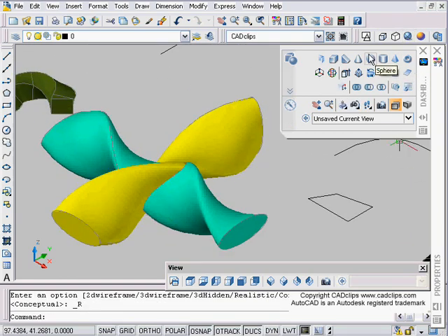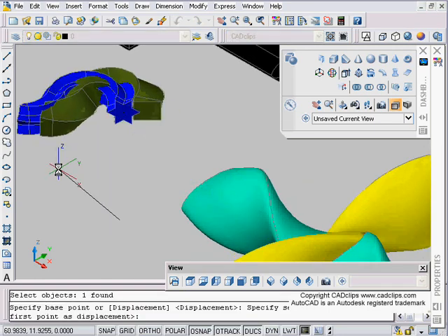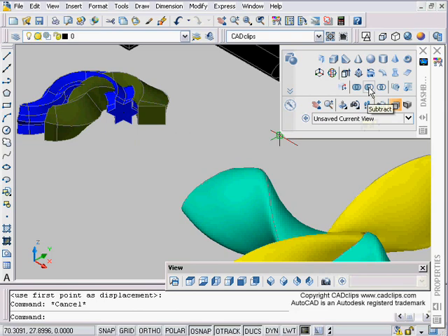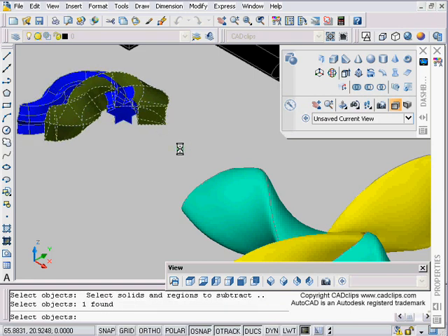Try it out, experiment, get creative, start to use all of these tools we've been talking about. Don't forget about our Boolean operations of intersect, subtract and union, where we can take these objects and blend them in with each other, and then maybe do a subtract from this, enter, this, and then it'll actually remove from that.